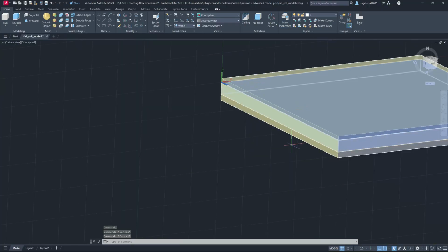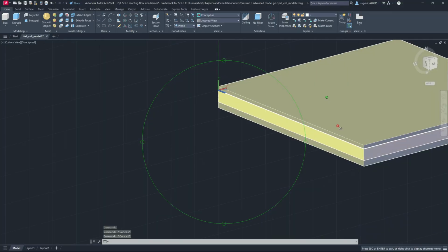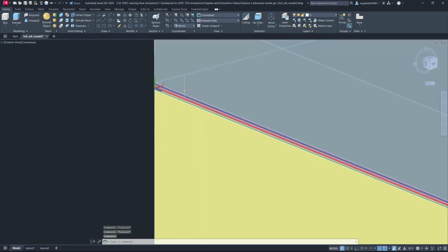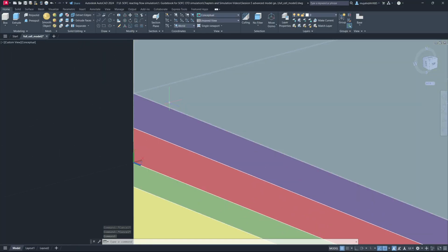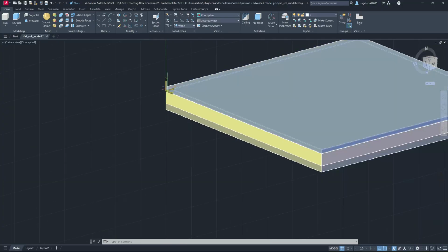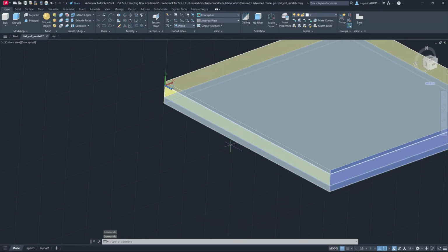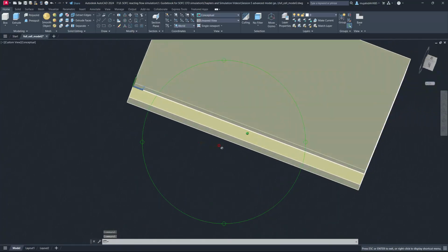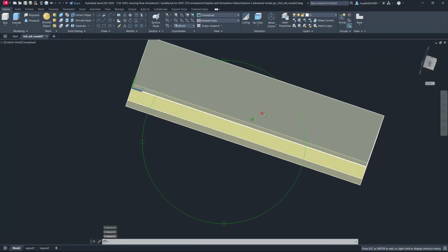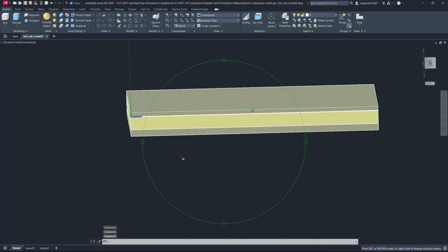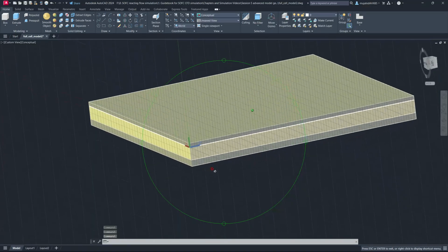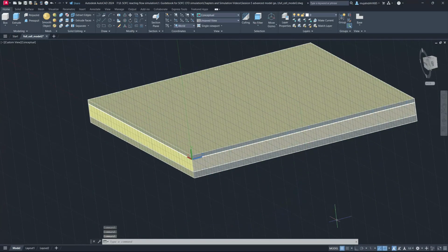So now we have a full model for the layers, and we need to make the gas channels and the interconnect. For making the gas channel, we'll first go towards the cathode side, and we need to make the gas channels towards the positive Z direction. And we should keep in mind that the gas channels, actually if we array them, we cannot make them into a single component or a single part. These are all different parts.